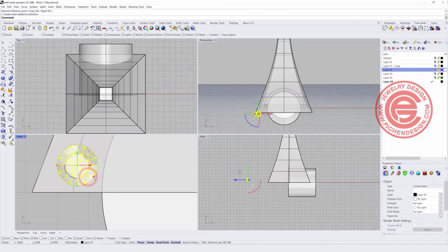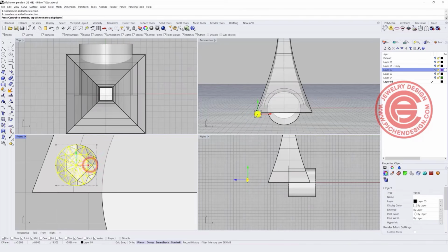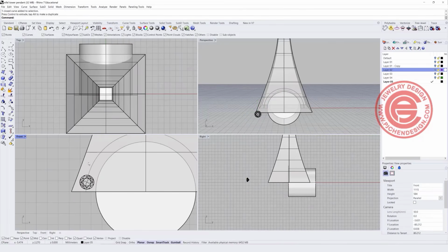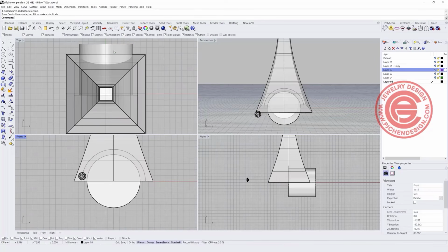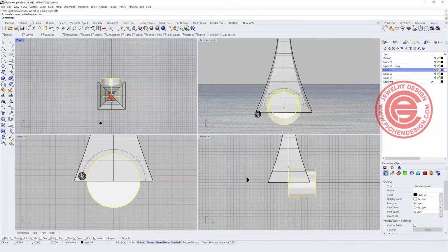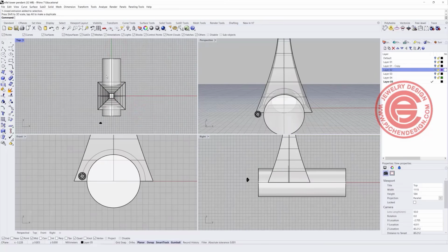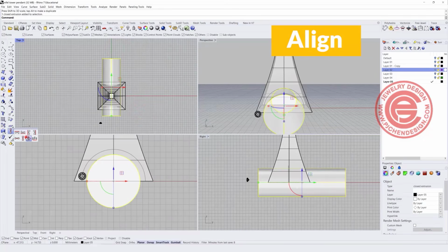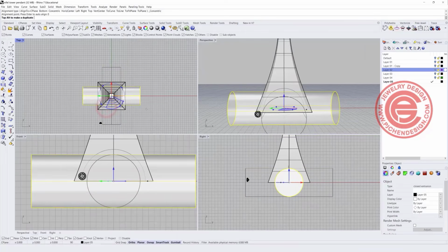And I actually want to move my stone to the right side a little bit. All right, so it looks all right for the proportion and everything. So I'm going to make the cylinder a bit longer and also have this cylinder aligned to the center. Just type 0, and also make a copy by using the gumball and hitting the Alt key.